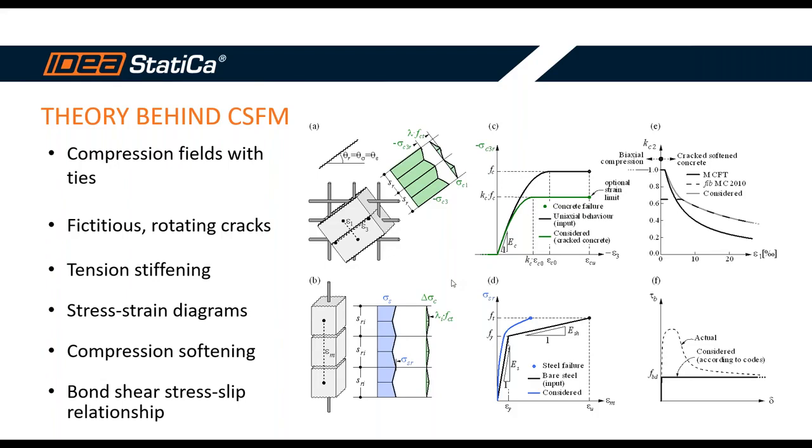So the theory behind CSFM, the compatible stress field method. From physical point of view, it is a compression field model with ties. The CSFM assumes fictitious rotating stress-free cracks that open without slip, and considers the equilibrium at the cracks together with the average strains of the reinforcement.